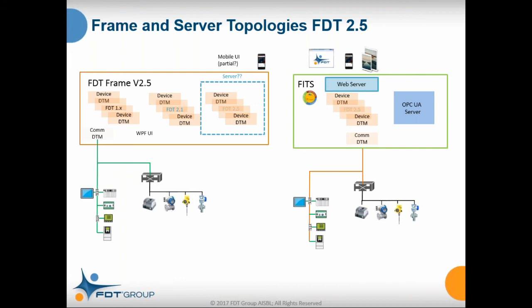A server serving up DTMs to mobile clients and being able to run apps on those mobile clients and to connect OPC UA to those devices. That's FITS. Remember, the operative letter in FITS is the S. It's a server. Okay, it is a server. It is not a desktop application. It is a server.